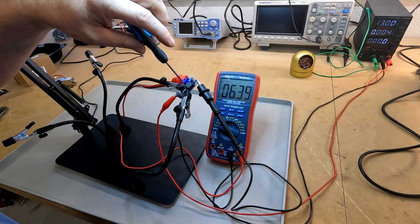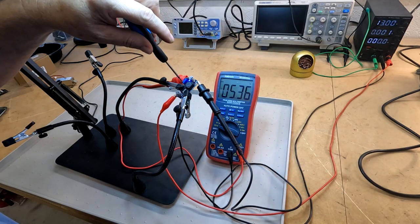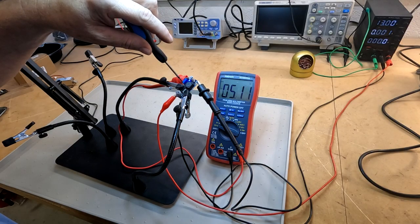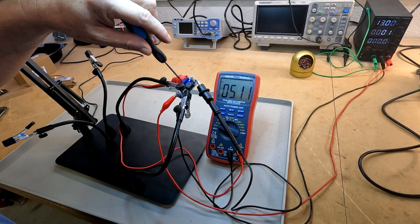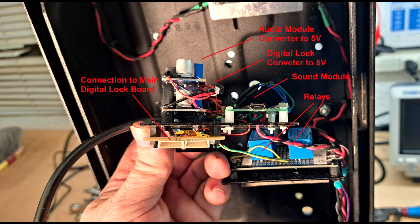For this, you will need to connect a voltmeter to the converter output. Turn the screw until it reads exactly 5 volts. Only then can you connect the digital lock and the audio module, or they will immediately burn out and you will need to start over. There is a possibility that the digital lock or the audio module could interfere with each other while sharing a single converter module. For this reason, 2 of these converter modules are being used, one for each. They are so inexpensive and easy to connect, there is no reason not to.